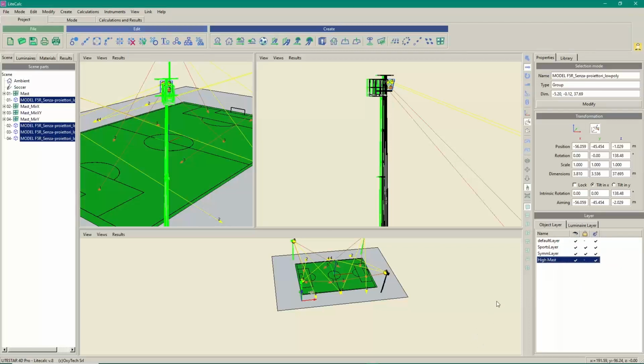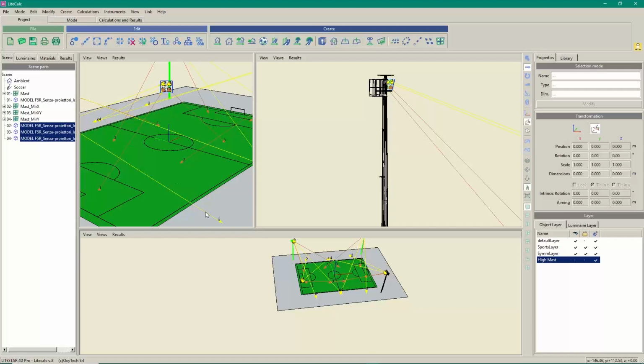And the selected object will be placed with right-click, assign selected object, and if we do not want to visualize them, we simply select this one. And so, as you can see, they will disappear. So only one disappeared because, yes, we made the symmetrization, and so these are blocked. Yes, this is a little mistake of the program.